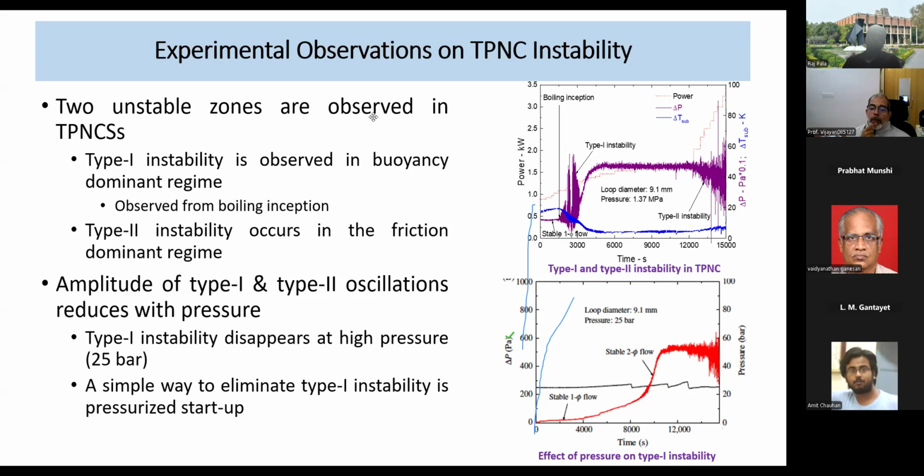And in thermal power plants, why they have preferred natural circulation over forced circulation is that many times they cannot avoid flue gas maldistribution. They found that in the channels having high power, CHF and oscillatory CHF occurred, and eventually the pressure tube fails.